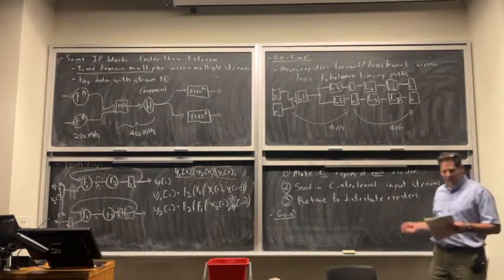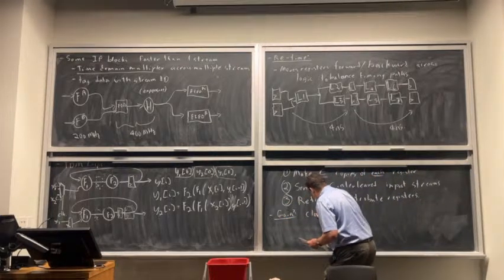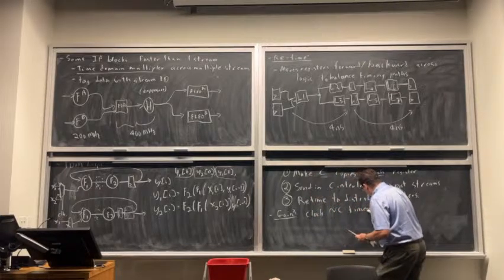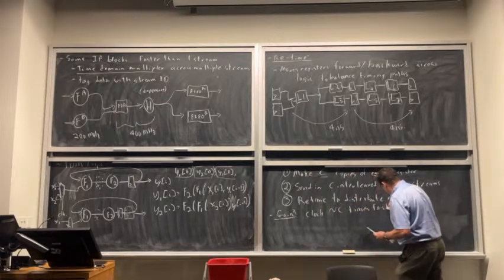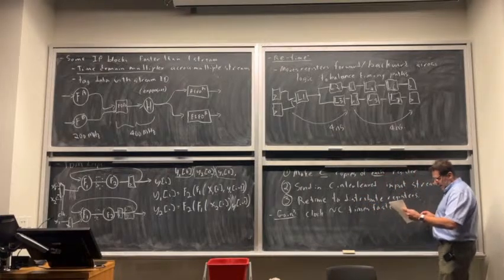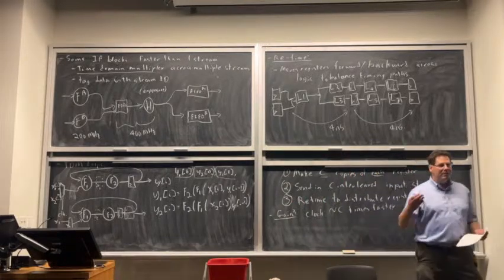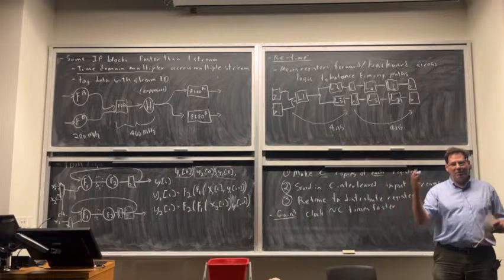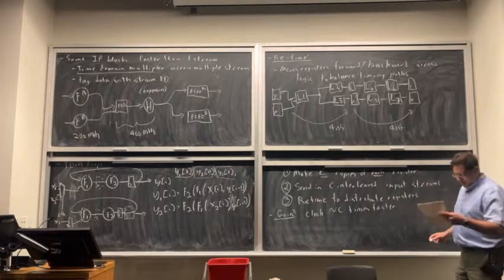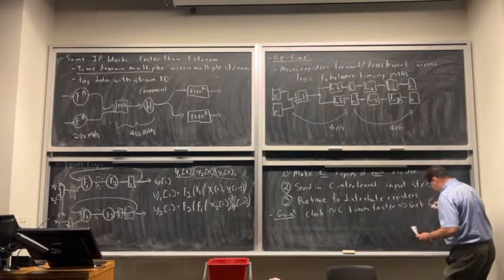Yeah, so if everything works out perfectly, you can clock it about C times faster. So that doesn't get you one stream through faster because you need C clocks between data elements of one stream, but you do get C of these streams through at once.